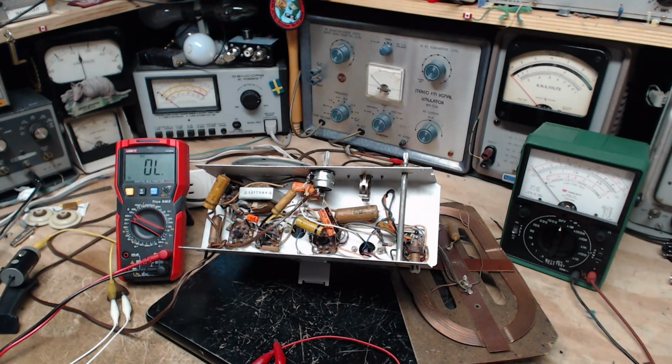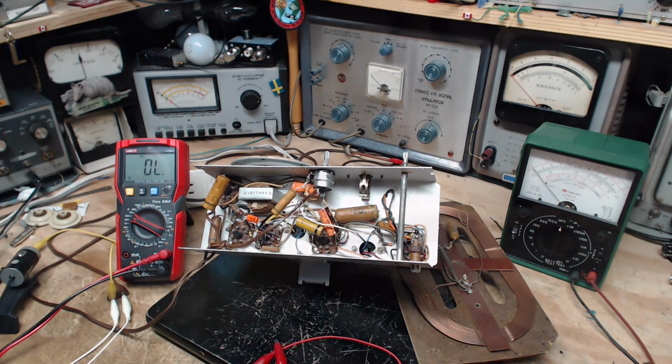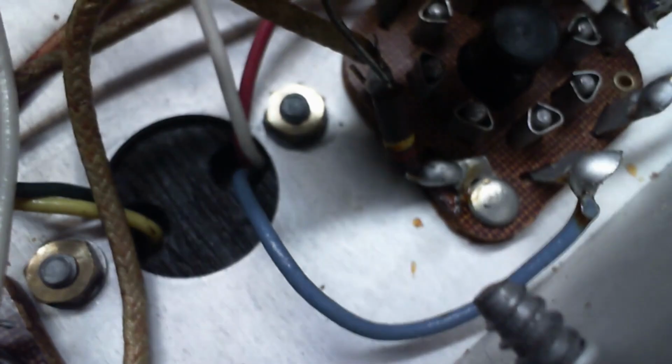Okay, well, I spotted that resistor. Pretty hard to see it because of the funny angle it's on, but it's right there. I'll put the close-up camera on it. We can take a look at it. Red. So there it is. Now you can see, well, I can put a little more light on it here. That should be red, yellow there. Hey, my lights aren't on here. Can't really see the other red, but no doubt that's red, yellow there, which would be 220K.